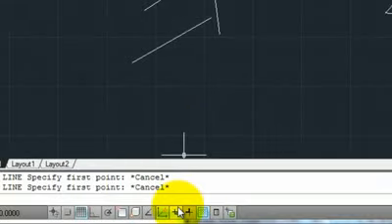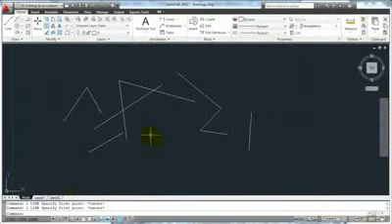Another thing that you can do is, down here on your status bar, there's an option for dynamic input. You probably can't see the little tooltip pop up when I move my cursor over there, but turning on dynamic input basically moves my command line up here to my cursor. If I have a blank command prompt, AutoCAD's ready for a command. If I go to my command alias for line and hit L and hit Enter, notice right here within my drawing, a little window pops up. It's kind of like a little snapshot of my command line. So instead of having to look down here, it's right up here where my eyes are already focused.